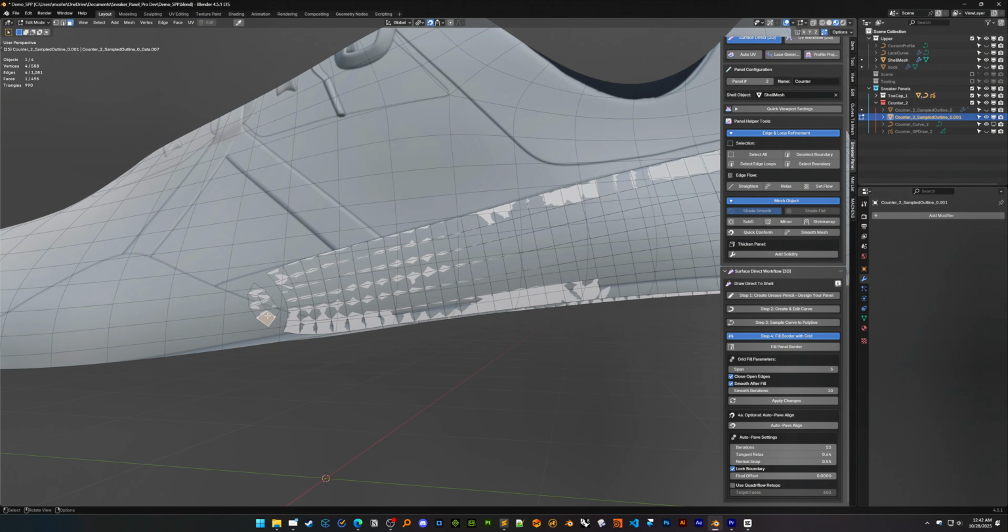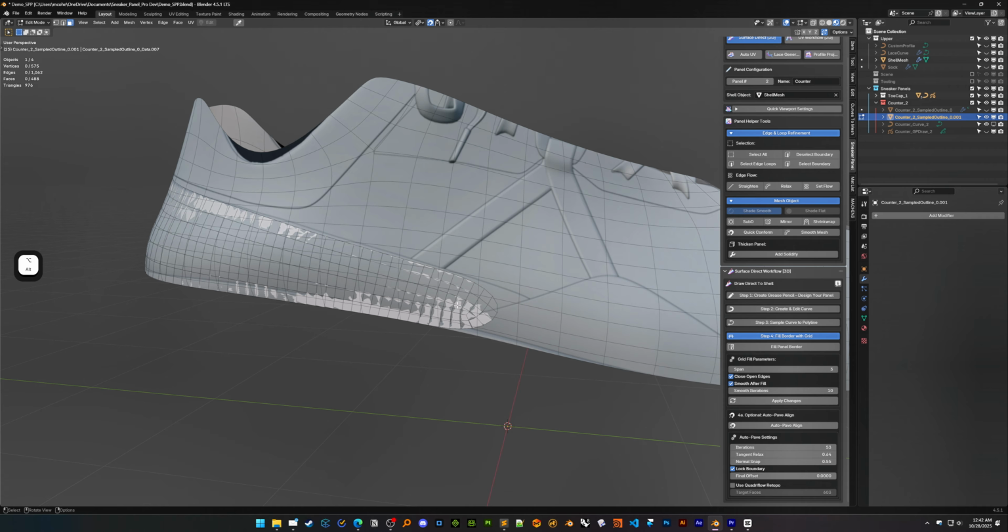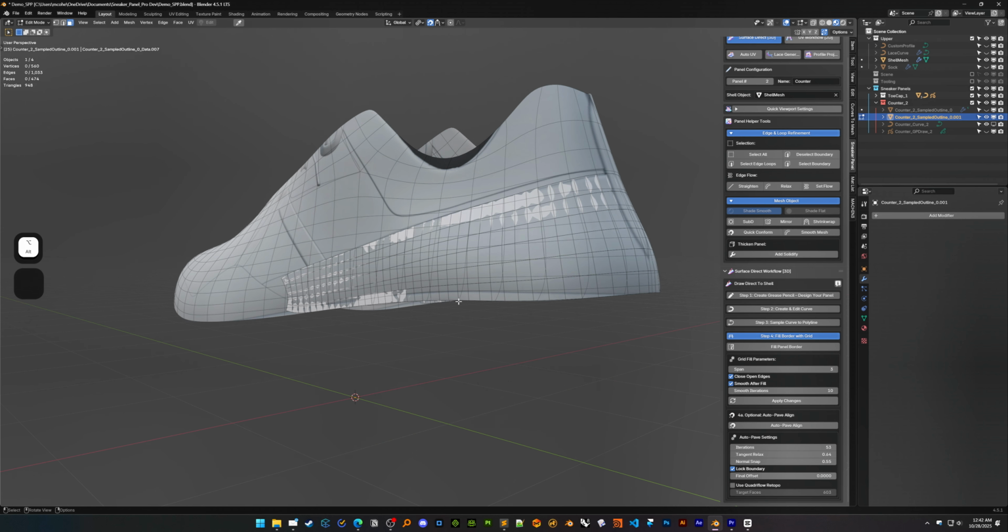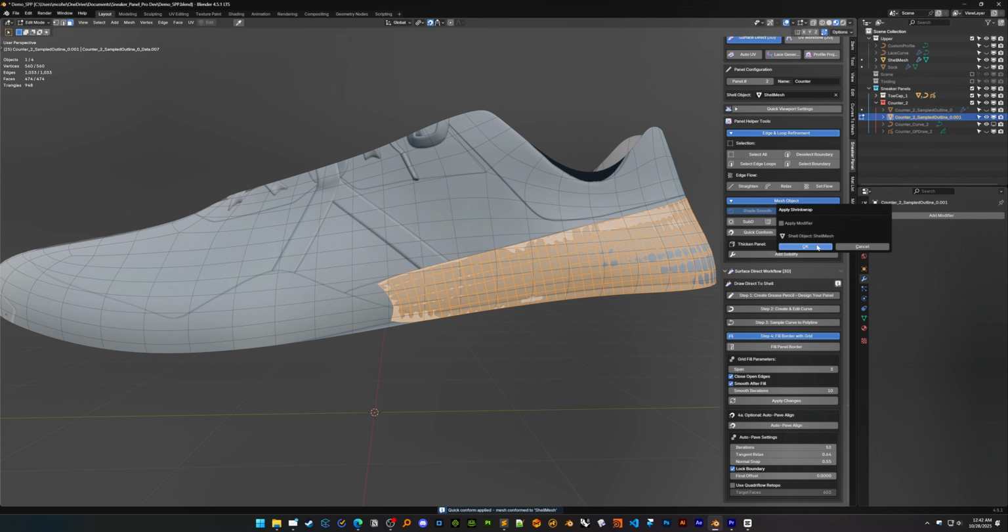This alternate method isn't required, but it's great for complex or irregular panels. Just remember, self-intersecting meshes won't remesh correctly. If your geometry folds back on itself, split it into separate parts and rejoin later using Boolean operations.